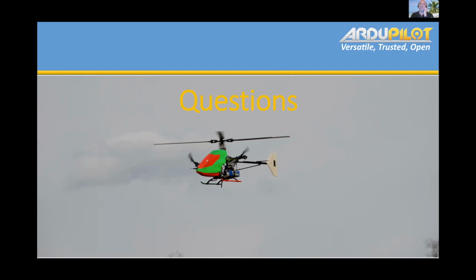And that's where auto-tune could be a huge benefit to heli users, because most heli users don't know how to even set their feed forward properly. At the moment, you need to do a flight, then examine your log and work it out with some maths and a very clear understanding of the way the actual controllers work to calculate that. It's very hard to just do it by eye.